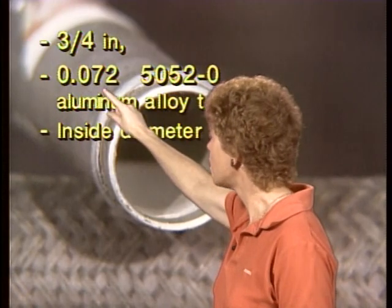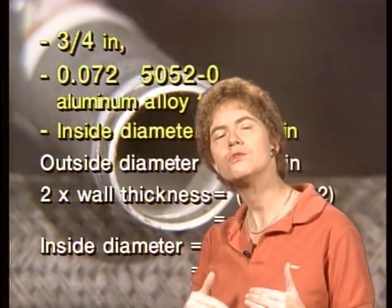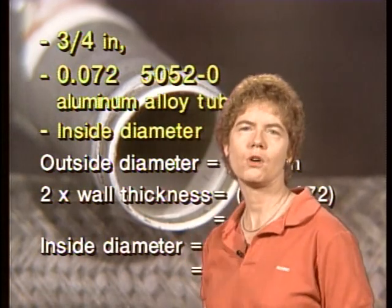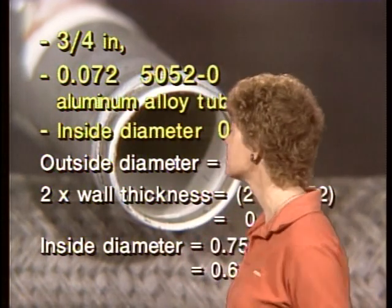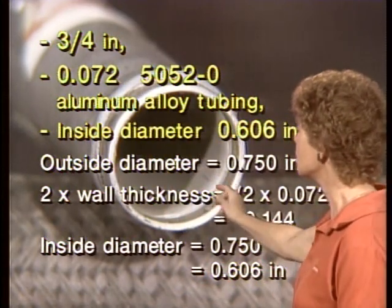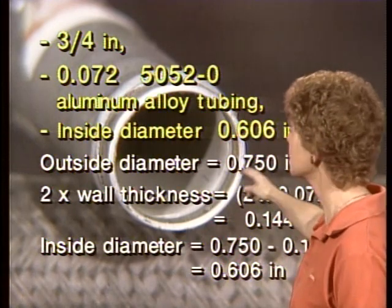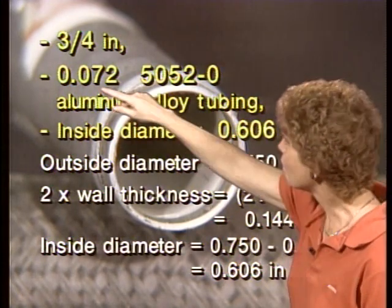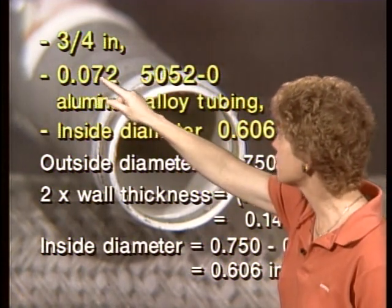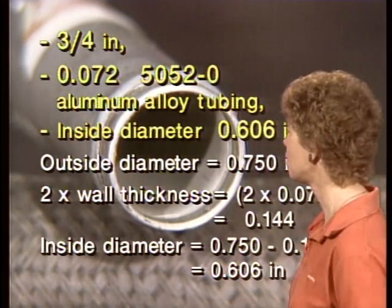The 0.072 is the wall thickness. And remember, we said that you're going to take 2 times the wall thickness and subtract it to get the inside diameter. Okay, the outside diameter, 3/4 inch, is 0.750 inches. 3/4 of an inch, 0.750. The wall thickness is 0.072, and what you need to do is subtract 2 times the wall thickness.